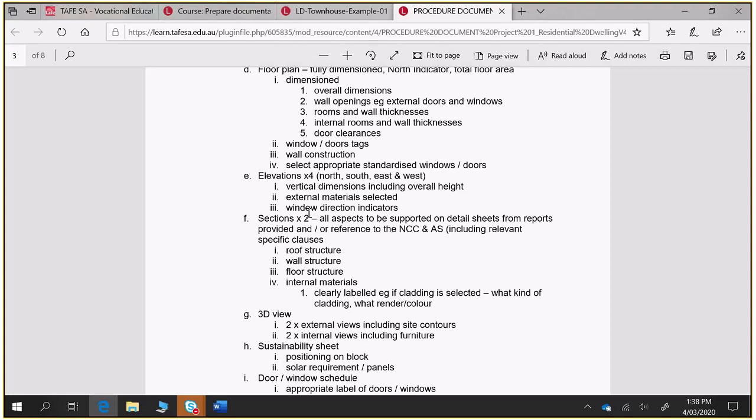But one thing I don't want to see you doing is drawing the trusses in accurately and the nail plates and things like that. Why don't we do that? It's information we don't even know. Someone else's responsibility to do it. Exactly. Someone else is going to do that, and they'll supply all that stuff. So you just put in an indicative W, your web, like a type B truss. That's it. And show that so it's enough information for someone to see.